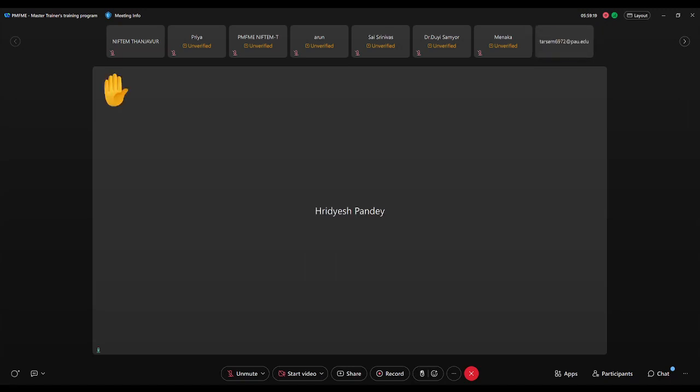Sir, I was interested in knowing more about this aloe vera machine and the processing of aloe vera. Can you highlight a little bit? Yeah, this aloe vera machine, which we developed about two years back in our Department of Processing and Food Engineering at Punjab Agricultural University, Ludhiana, has been recommended for gel extraction. The main purpose of this machine is to remove the outer rind of the aloe vera leaf, so that we can extract the gel.